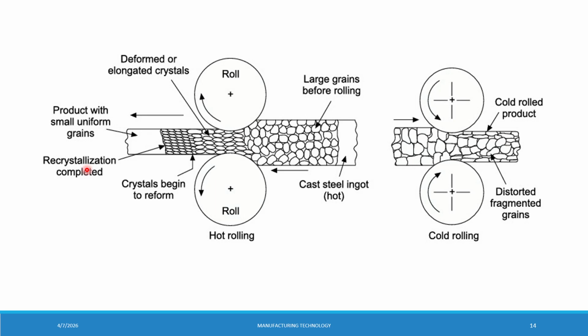Now some of us, after we get these products, are not happy with the surface finish on the top and the bottom. As I told you, this temperature was at recrystallization temperature. As it cools down, the top and bottom layers react with the oxygen present in the atmosphere and form metal oxides, in the form of scale or rust, which we actually don't want.